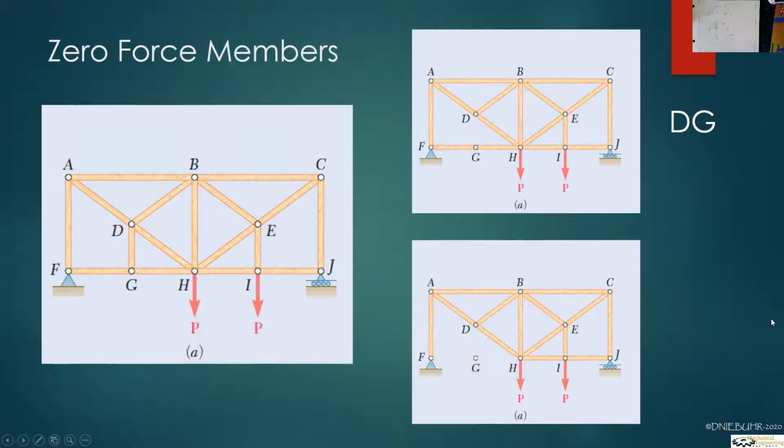But you can see that the truss is still statically stable with this because F is supported at A. And since there's no lateral force on it, we don't have to worry about it tipping over. But we can't guarantee that's always the case. So we got rid of those. And so the same can be held true now if we go up to DB.